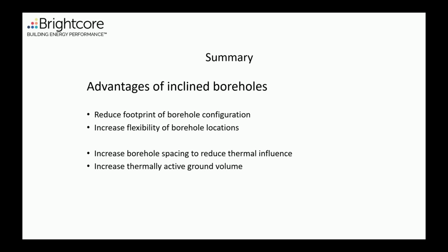And to summarize, the advantages of inclined boreholes is to reduce the footprint of the borehole configuration, and that also increases the flexibility of the borehole locations. You can make them kind of regular, deeper down, but you can put them in better positions at the top.